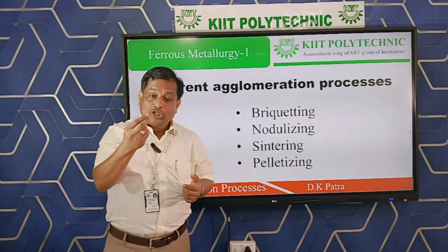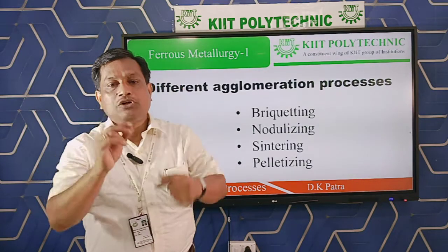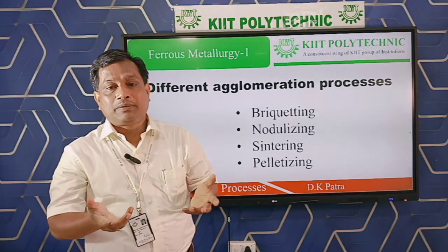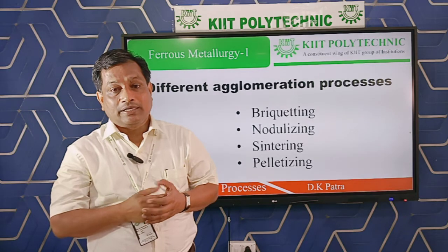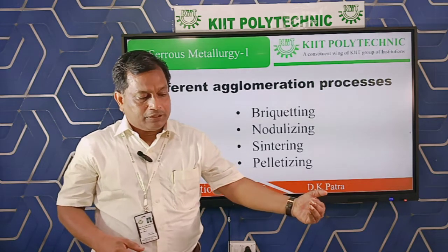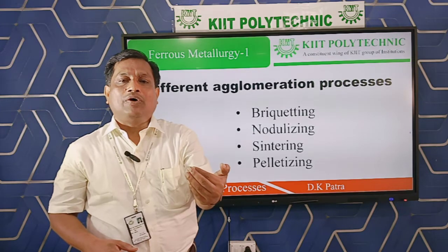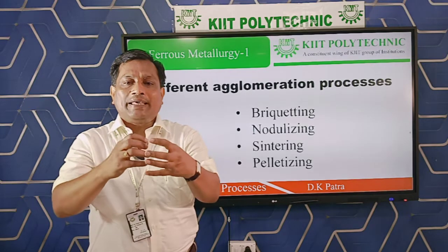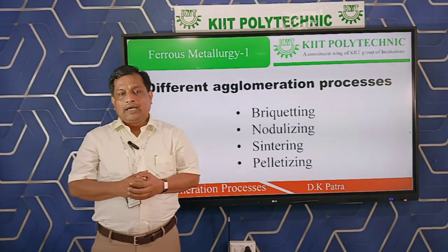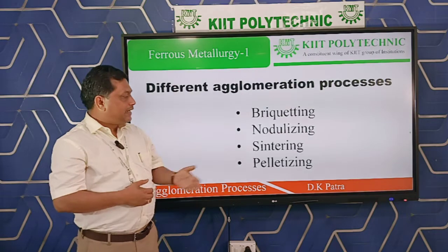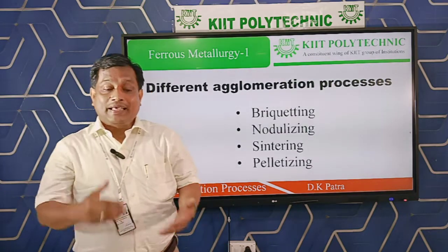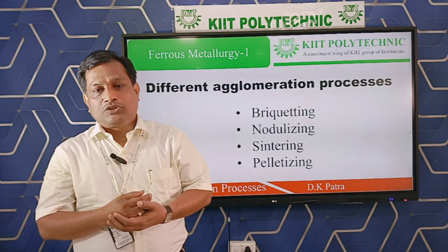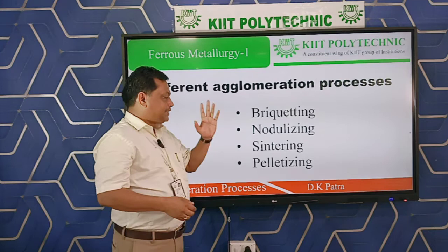Whenever it is traveling, due to the rotating motion, small balls or granules of the iron ore will form with the help of the binder, that is bentonite as well as tar. From the bottom of the rotary kiln, we supply gas or oil, burning it to help develop high bond strength in the material. After 2 hours, we have generated a lot of nodules of the iron ore. But again the same problem came: high density and lack of porosity. That's why this is also rejected.